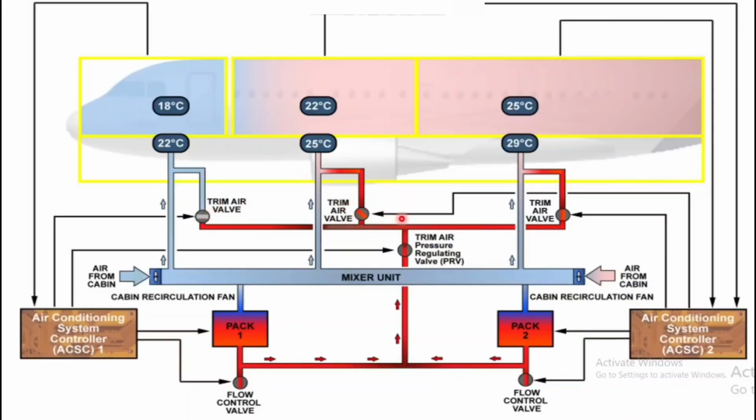So this can be independently controlled from the 3 position switch. So you can mix the hot bleed air into the mixture unit, and then it will control the temperature. And this is your cockpit zone temperature. This is forward cabin zone temperature, and this is your duct temperature. So the lower ones are all duct temperatures, and the top ones are all zone temperatures.